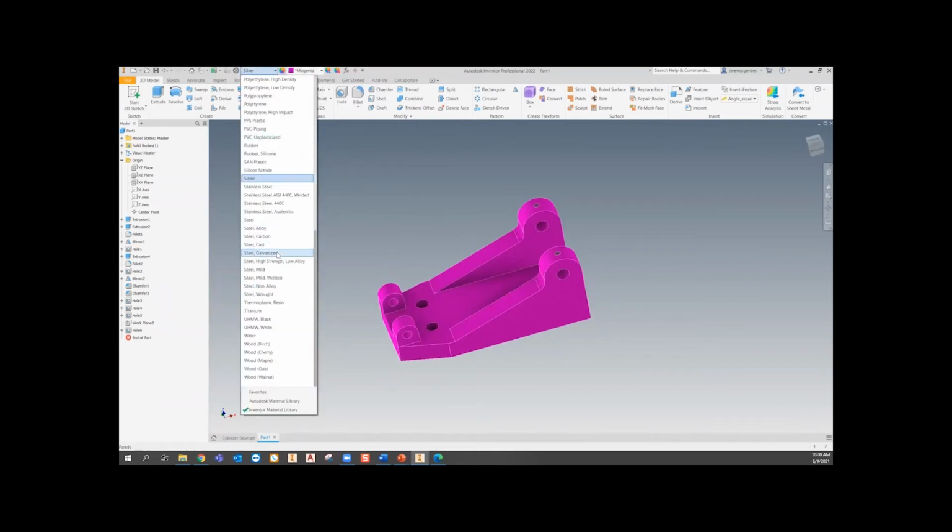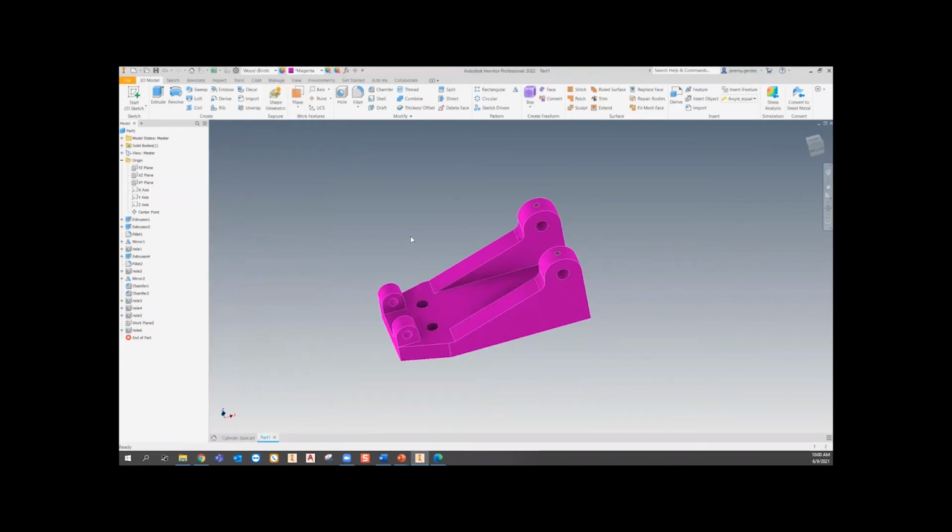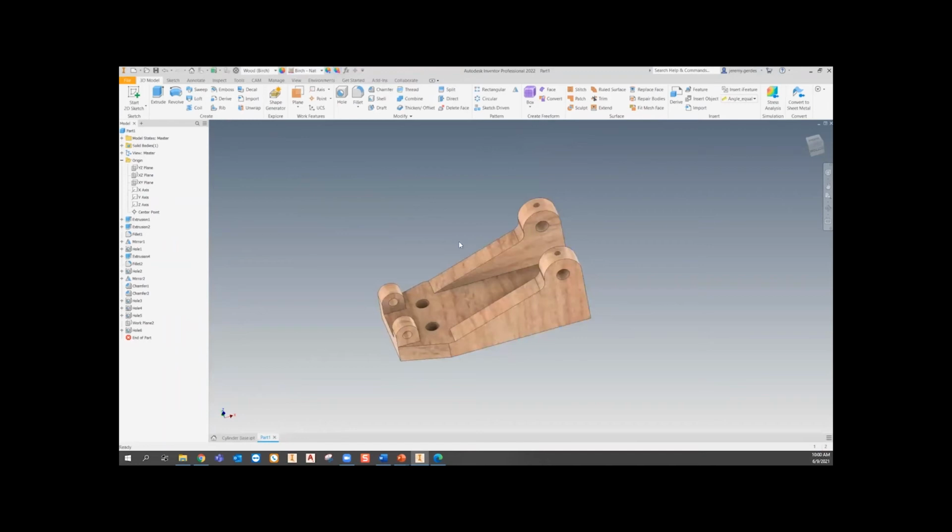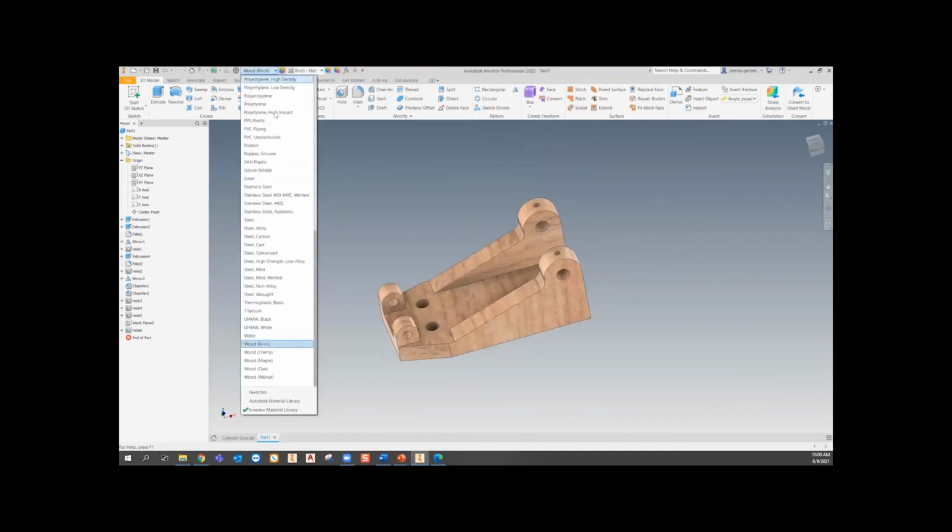And then the appearance, since it was overridden, stays at whatever I selected, even if I change the material. So if you're changing the material, you're like, well, why isn't it showing a new appearance? It keeps it stuck on this. One thing to always check is if you have a little star next to the name, it means that's overridden. If you come up here to the clear, select all. And then it goes back to following the material.